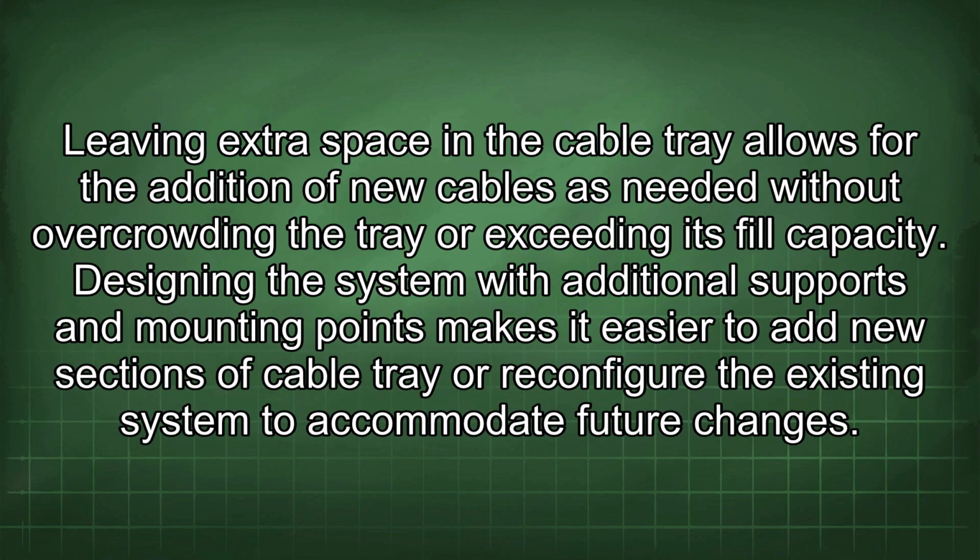Leaving extra space in the cable tray allows for the addition of new cables as needed without overcrowding the tray or exceeding its full capacity. Designing the system with additional supports and mounting points makes it easier to add new sections of cable tray or reconfigure the existing system to accommodate future changes.